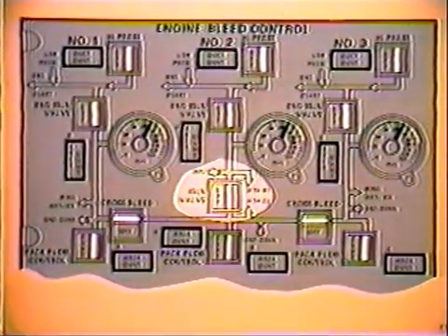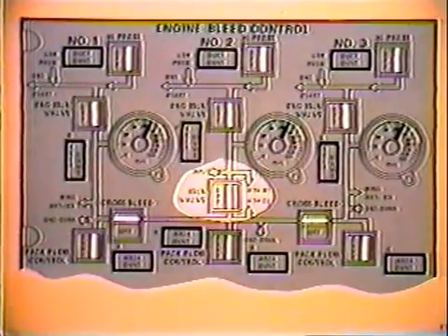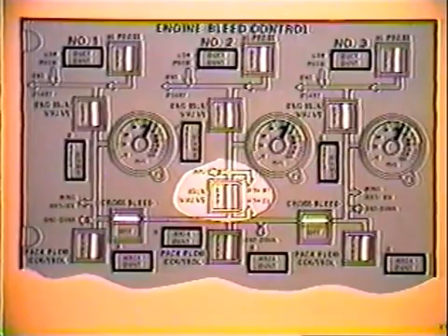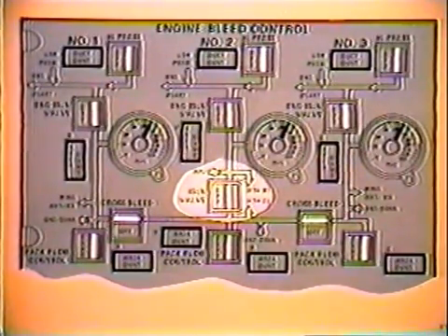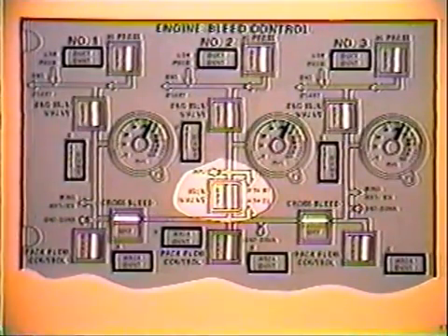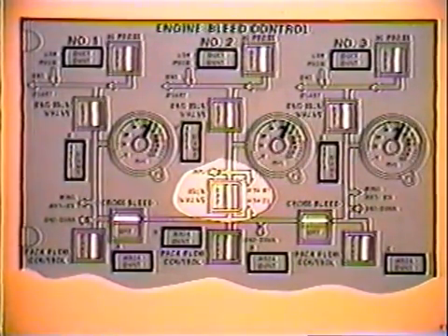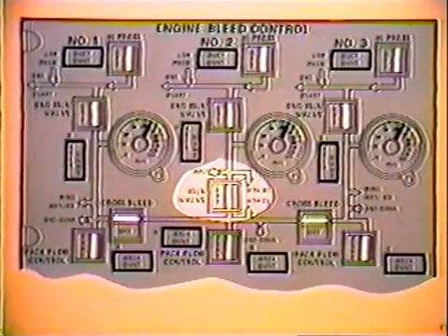The remaining valve in the pneumatic system is the aft fuselage isolation valve. Its primary function is to provide the capability to isolate portions of the manifold so that a leak in one area would not necessarily cause a loss of pneumatic pressure to both air turbine motors.